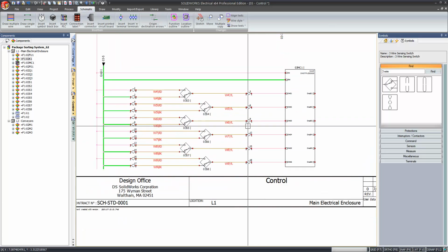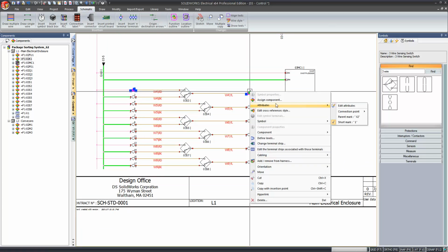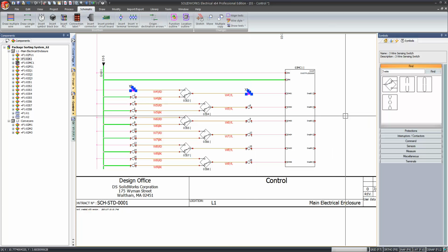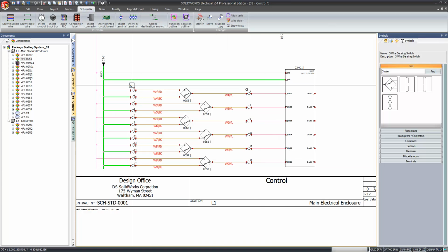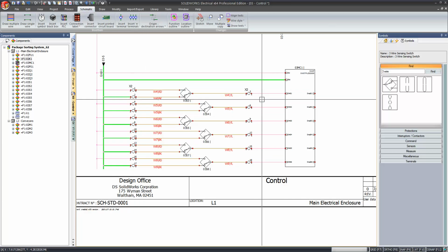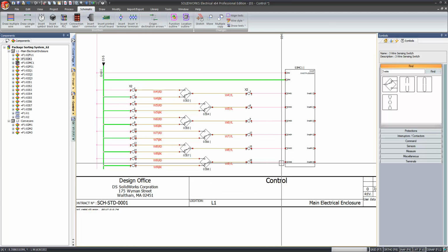And finally, these top 2 terminals, numbers 1 and 3, let's go ahead and show the parent terminal strip mark. So we know this is all terminal X2. So if I hadn't hidden that X2 terminal symbol beforehand, we'd see X2 on every one of these and on every other one of these terminals down the left, so it would be kind of messy.